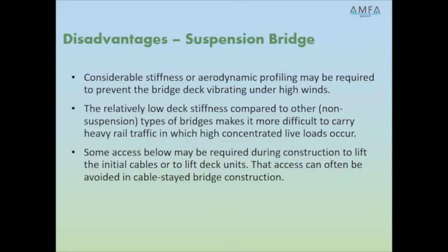A few disadvantages are that it has to withstand high aerodynamic wind load. In those areas, aerodynamic stability is a major requirement. A heavy wind can really cause havoc. There is also relatively low deck stiffness compared to other types of bridges, which makes it more difficult to carry heavy rail traffic or heavy live loads.